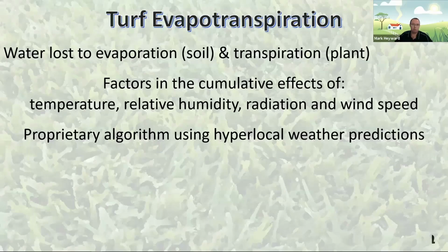The second part of the Phytech service is evapotranspiration calculation. These are done for turf. Turf is used as sort of an industry standard because it's a two-dimensional crop. It's evergreen, we don't have to worry about row spacings. It's shallow rooted, doesn't have a fruit load, and we keep it mown every few days. So we calculate the theoretical loss from your operation as if you're a turf farm, basically.